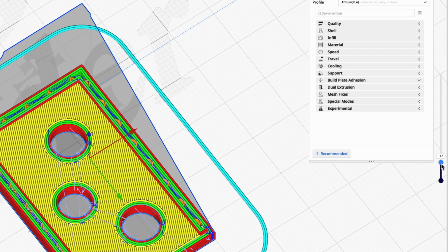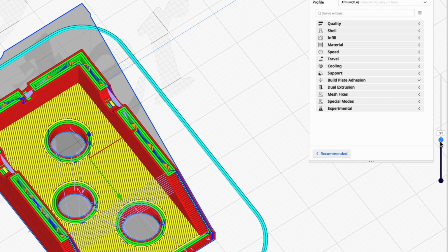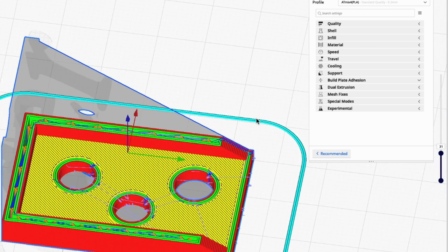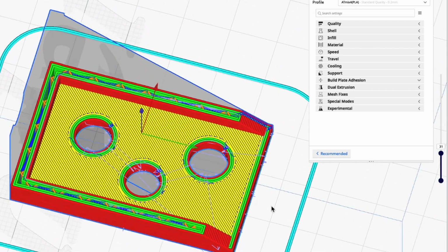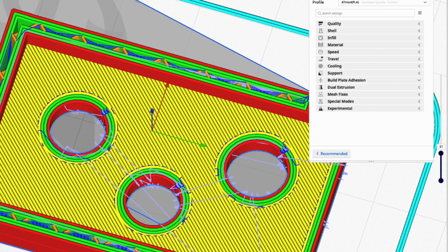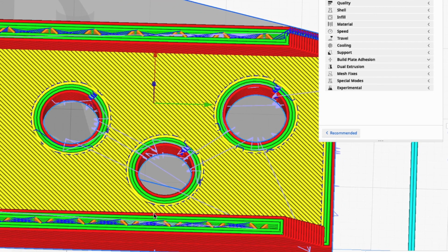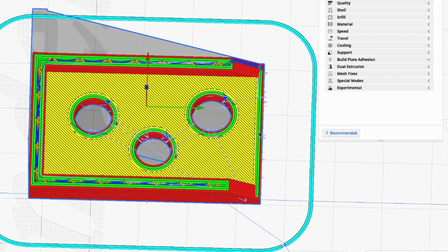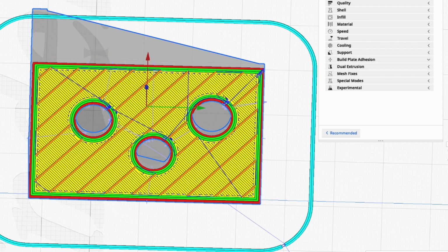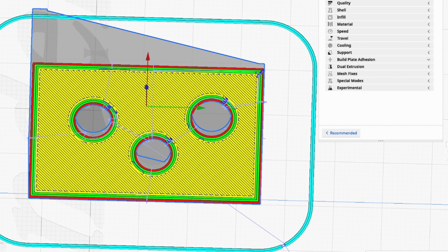And so, you'll get better with this, and you'll learn what to pay attention to and what not to pay attention to. But one thing to notice is the reason why I'm printing this model in this orientation is because I want to have, you see how these long strands, I guess you could say, or these long runs of plastic, we're printing the bottom plate pretty much all in one go. So we're going to do, I think, 3 layers.